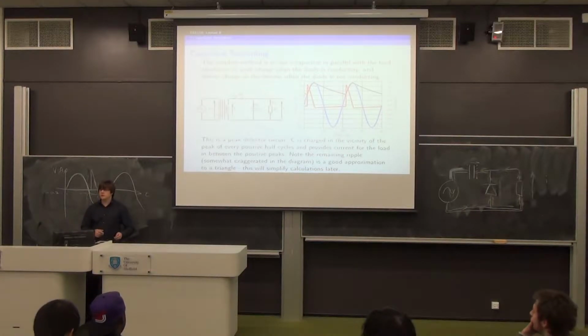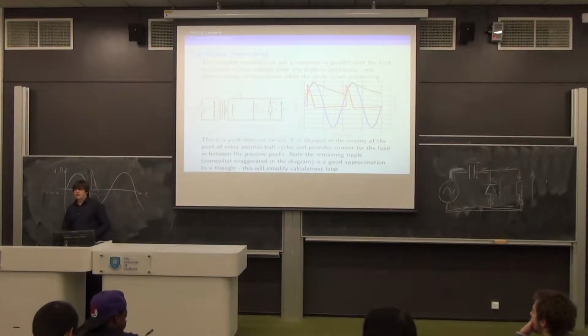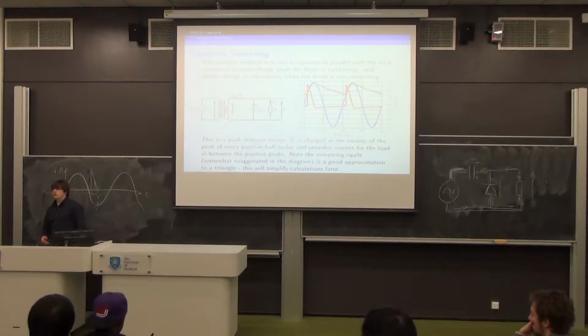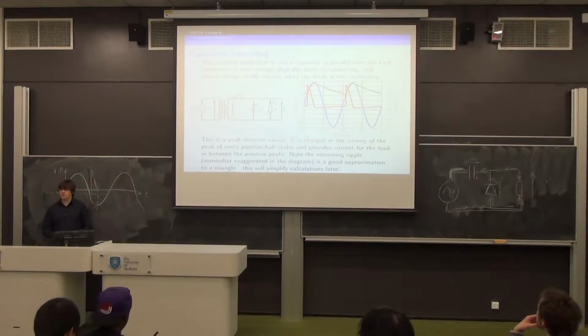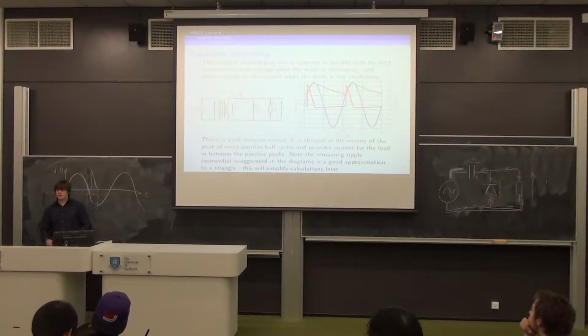So if we were going back to what happens if you run a motor off this and try and stall it, our torque situation has got even worse, because now your torque is in really confined regions and the vibration is going to be a lot worse. So actually we've smoothed out the voltage and we've made the situation for driving load more difficult, possibly.